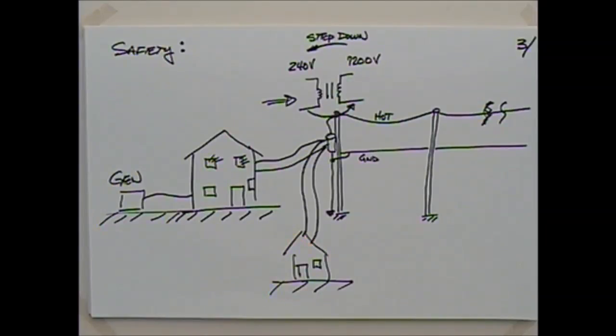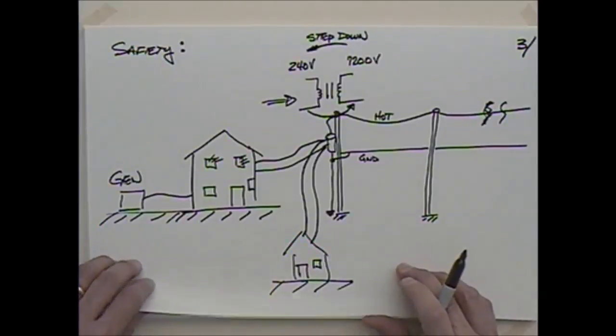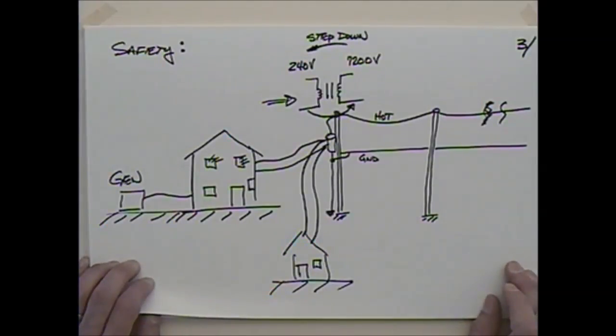Okay. This was also true in the laboratory that you did this week, right? I said when you had that transformer and you didn't know whether it was going to step up or step down, you want to start testing it with a very small voltage, right? Because if it happened to be 1,000 to 1 step up and you put in 1 volt, what would you have out at the output? 1,000 volts. Okay, so you want to start very, very low when you're experimenting with that. And this is something that comes up quite often with transformer safety. Questions with that? Okay.